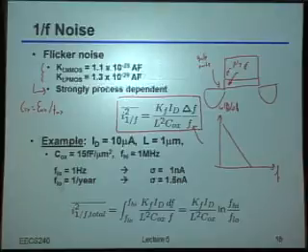Okay, well, here's the second question for you guys. Why is it also proportional to 1 over the length squared? How does that happen? And by the way, I'll give you a hint. This is similar to the discussion about why the drain current density in a long channel device was proportional to VGS minus VT squared, and that there are two independent mechanisms that are both proportional to the length, or 1 over the length. So how might having a longer device help you to reduce this noise?